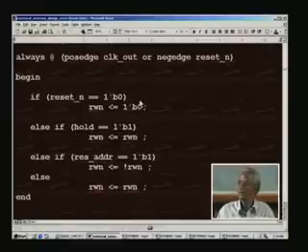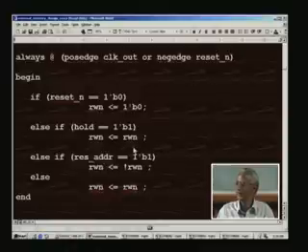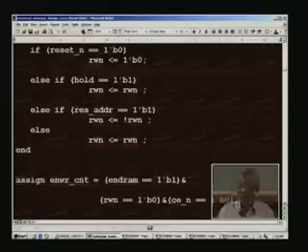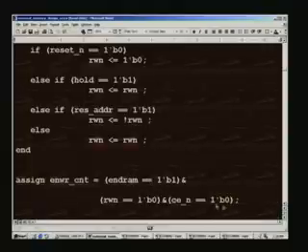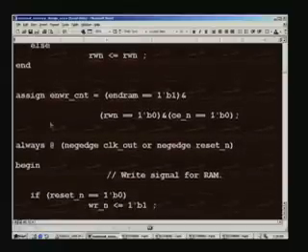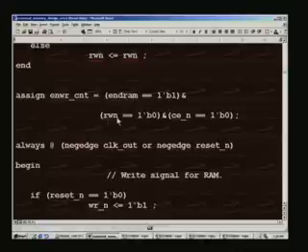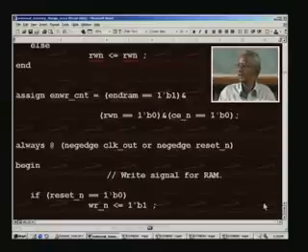And as usual we have taken the reset and hold condition. So, this is initialized to 0 here at the power on reset, and when reset address is encountered, what we need to do is just invert this RWN, because we can access the next external RAM in the case that we have dual RAM. So, we need an enable for write counter, and that is derived from the enable RAM being high and RWN being low, which corresponds to write here, that is why we have a write counter here, and also CE, the chip enable, must be active.